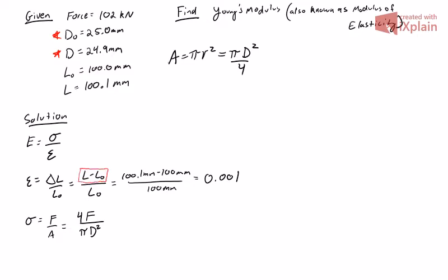When we calculate stress, the diameter of our object is constantly going to be changing as we apply more and more force. So if we were to use that constantly changing area, our stress would be calculated by a constantly changing force as we apply more and more force, as well as a constantly changing area. So we'd be varying both things in that relationship that calculates stress.